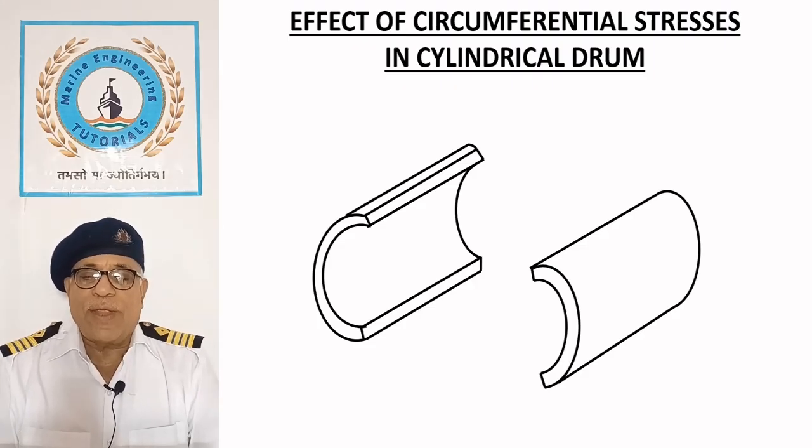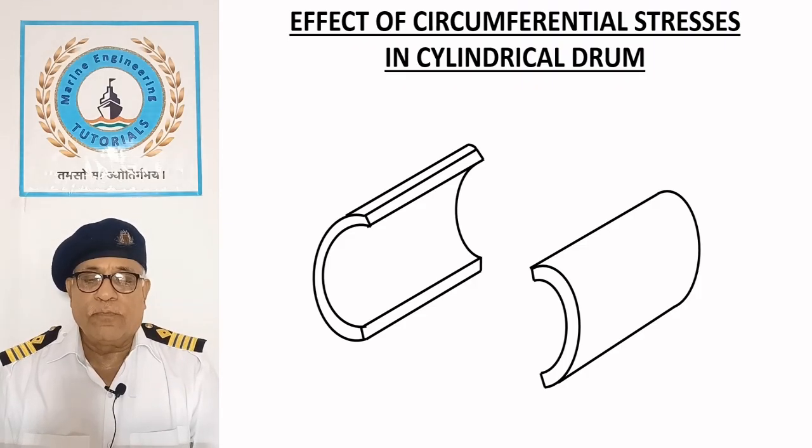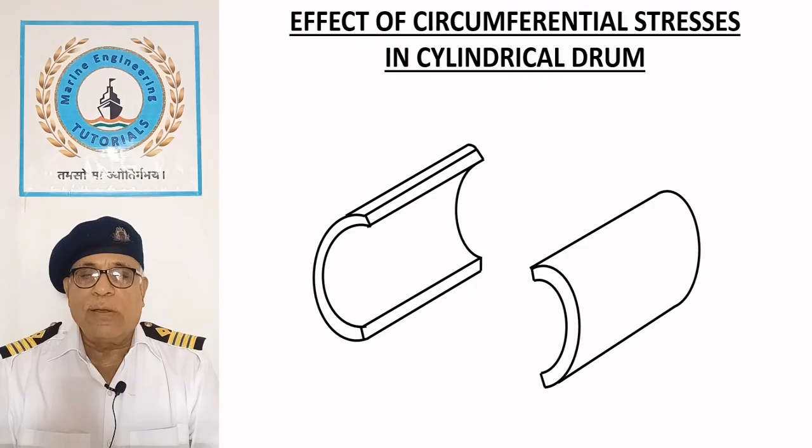It is important to understand the value of these stresses when designing a pressure vessel, such as a boiler drum. Care must also be taken to prevent excessive loss of strength caused by cutting holes in the drum for fitting tubes and mountings. The boiler drum is made by rolling at least two plates into a round shape and joining them with double butt welds along the longitudinal axis.